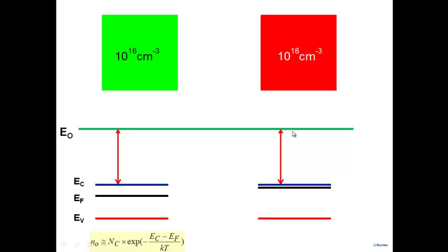As it comes down, now note, because electron affinity is a constant, the whole diagram that you see from here to here starts coming down, right? Eventually, as more and more electrons transfer, this EF will line up with this EF. And as it lines up, equilibrium has been attained, no more flow of current. So this is what is happening now. Electrons are flowing from higher Fermi energy to lower Fermi energy. And this is what is creating a field, a potential difference, and this part starts coming down.